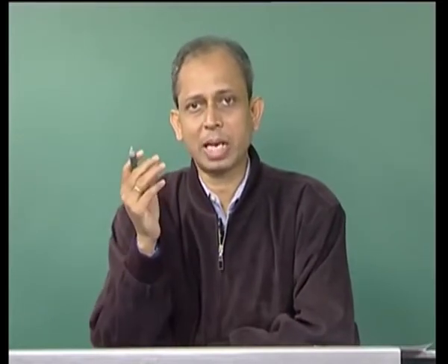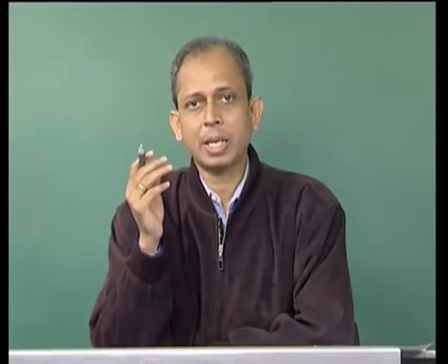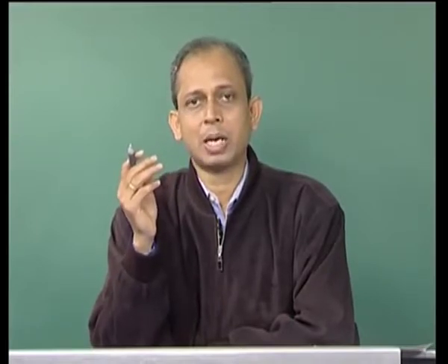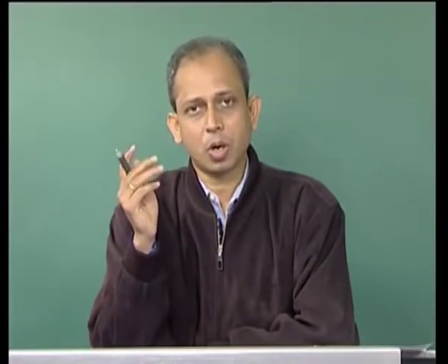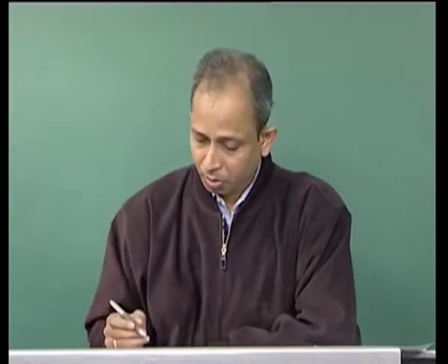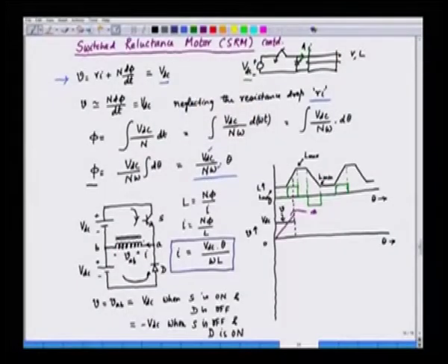Speed can also be a variable. So, I is not only a function of theta, but also a function of the speed and the inductance, also the applied voltage. So, under this situation, we can say that I will be proportional to VDC. So, it is basically proportional to VDC, but it increases with theta also.